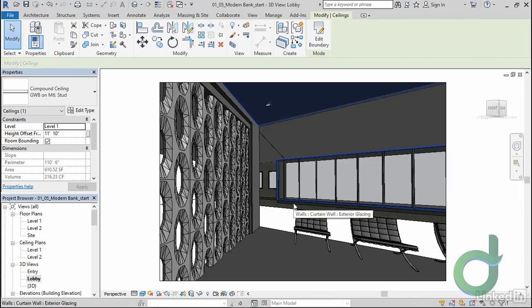And this really illustrates why we want to break up these large surfaces. What I've done by breaking this up and then planning in those can lights is allow this to connect very nicely in shorter runs to the corner and other places, rather than seeking out the nearest vertex, which may be way across the room, would get me huge, long triangular faces. We can add in other round objects in this if we need. We could put in more recessed cans, maybe in offices, or start to add in surface mount fixtures. It's important, though, again, to really start to break up the large objects so they light nicely.